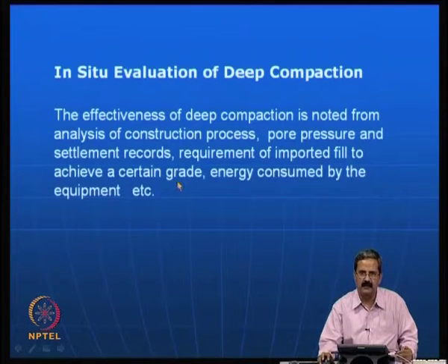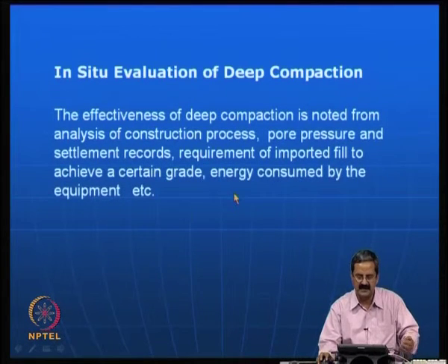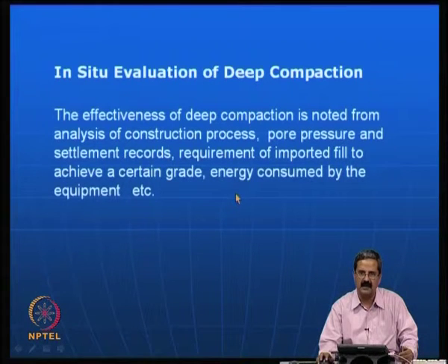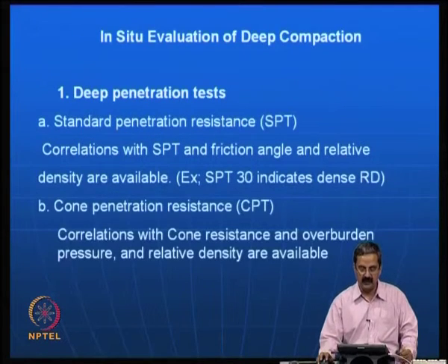Then another variable is the energy consumed by the equipment itself. For example, the energy that you put into the soil system has a very good influence. The higher the energy transferred to the in situ system, the more efficient the process of compaction. So, you must be able to analyze every bit of this information and come out with a proper understanding. If you want to quantitatively evaluate the state of the soil after deep compaction, you must go ahead with some tests.